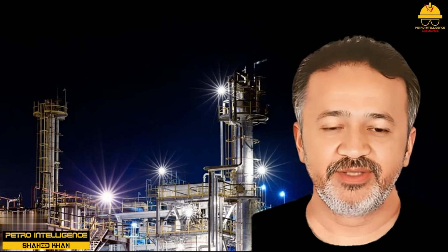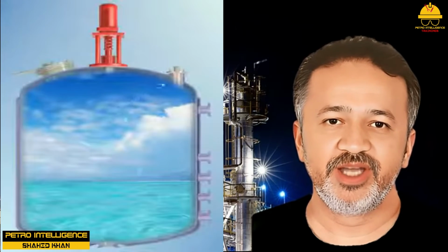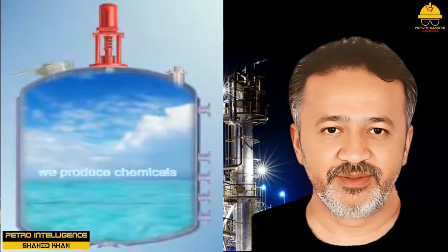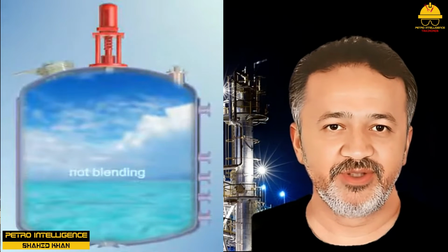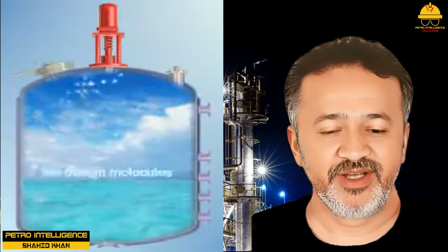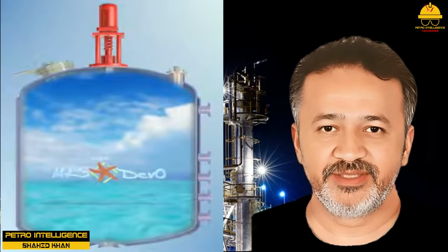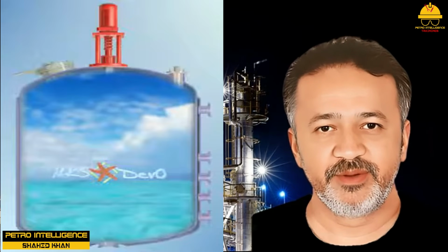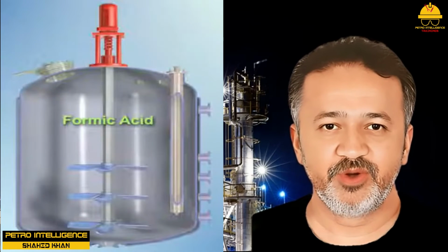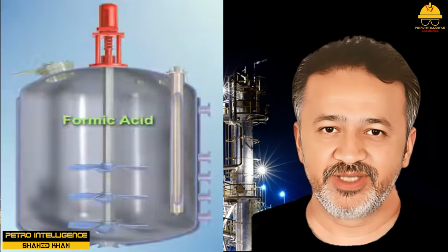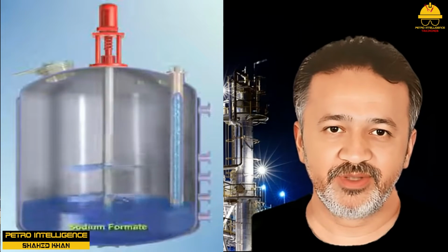Introduction to reactions. A reactor is a vessel in which a controlled chemical reaction takes place. This chapter discusses 5 basic types of reactors: stirred tank reactors, converters or fixed bed reactors, fluidized bed reactors, tubular reactors, and furnaces. There are many other types of reaction vessels, however, most of them are simply combinations of those 5. The various things that have an effect on a chemical reaction are called reaction variables.